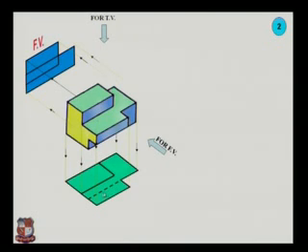Now the new thing is the hidden line. The hidden line can be drawn when the object is hidden. For example, when we see the top view, this extra portion or the hidden portion of the base cannot be seen. It is invisible from the top view. That is drawn by the hidden lines. Now we will see the orthographic projection in the first angle projection method.